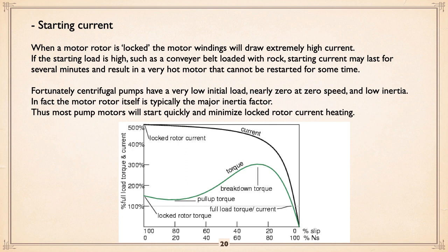So you can see we've assumed here there is some line loss. In other words, not 600%, but with line loss, and because the voltage has dropped off a bit, the motor is at 500%. This is typical of motors. So we're seeing this very high current when it's locked. At that same situation, zero speed, the current is quite high, and the torque is also very high. So we've got locked rotor current and locked rotor torque.